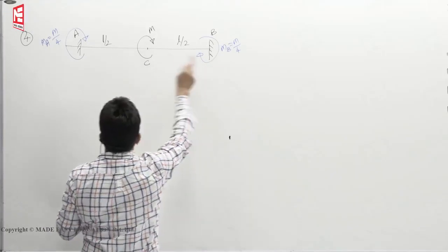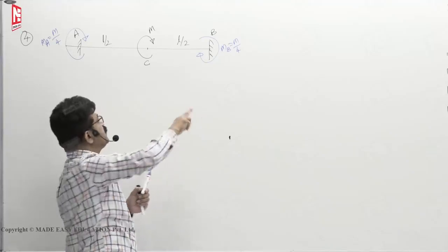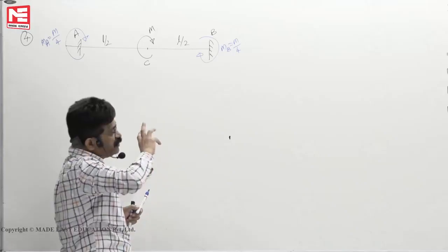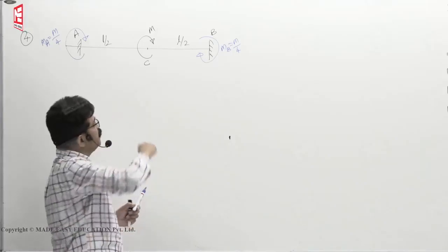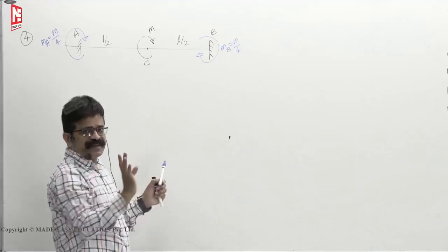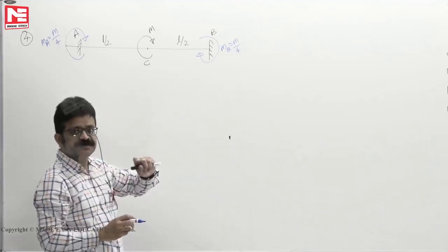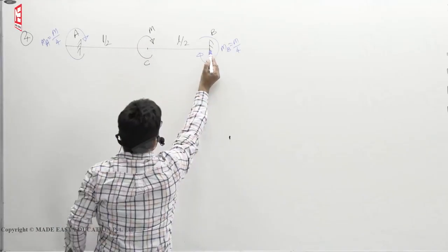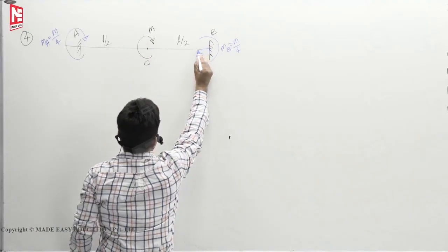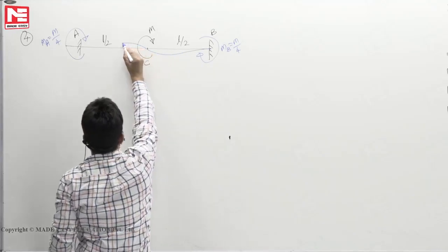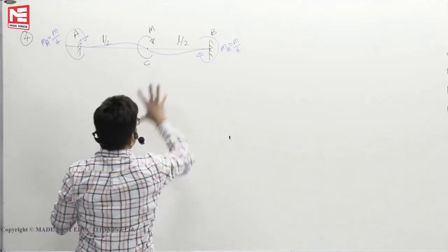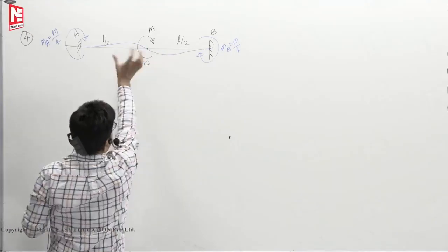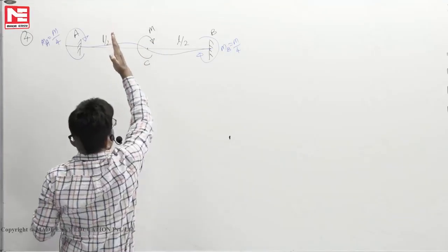This purpose, as I told you, MA, MB purpose is not to balance M. Their purpose is to make the slope 0. In the process of making the slope 0, the applied moment and reacting moment are in the same direction. We will see the deflected shape, then you will know why it is developed in the same direction. When I turn it like this, the deflected shape will go something like this. See how my fingers are moving. Right side down, left side up. So accordingly it will deflect. This goes down, that goes up.